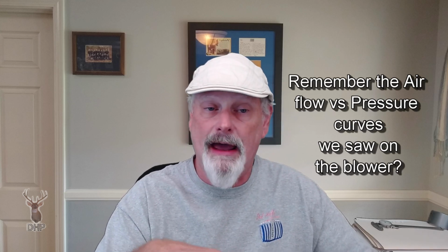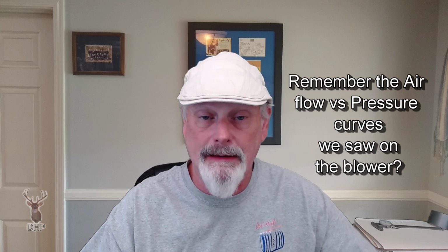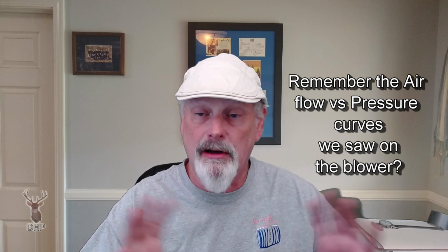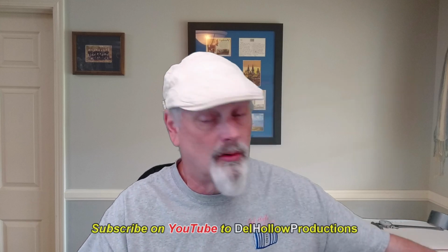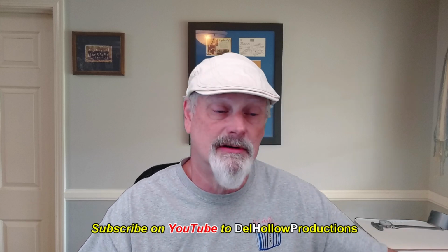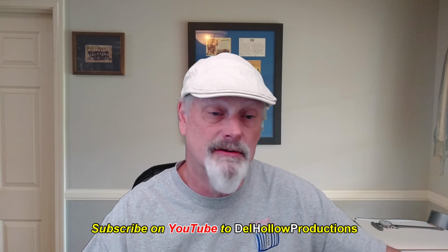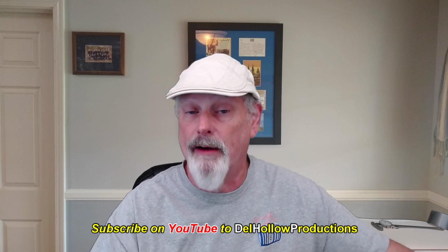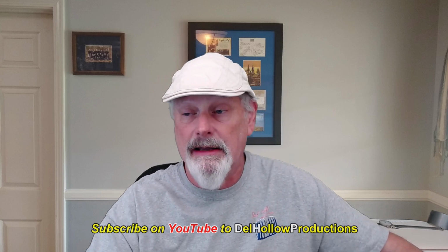That's why a lot of these low-speed fans work a little bit better, because one, they don't make much noise. If you had them by themselves and plenty of room for it to breathe, they'd move a lot more air. But you close off that box and it's the pressure effect. The so-called high pressure units are maybe cut a little bit closer, the geometry is a little bit different, whatever it takes, it can just go to a little bit more pressure before it cuts off.